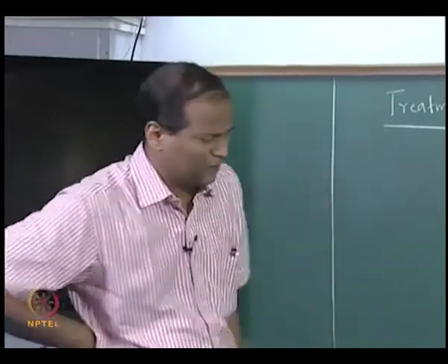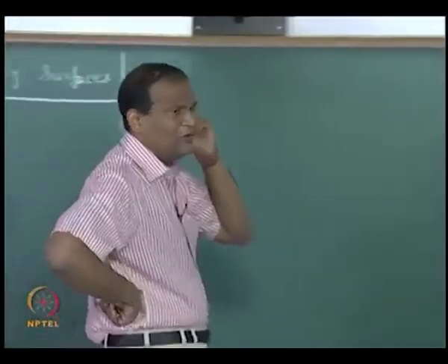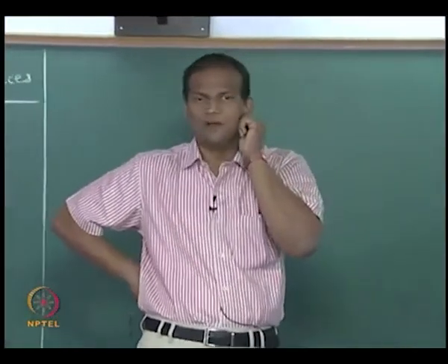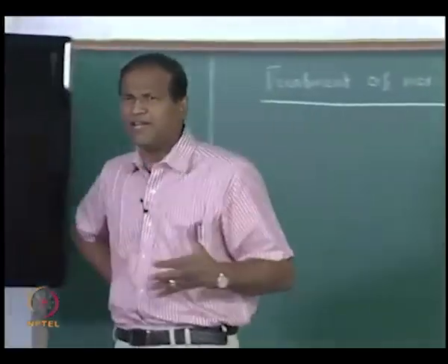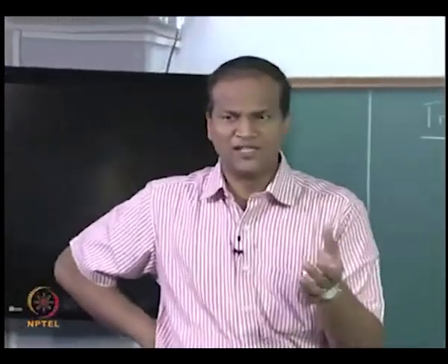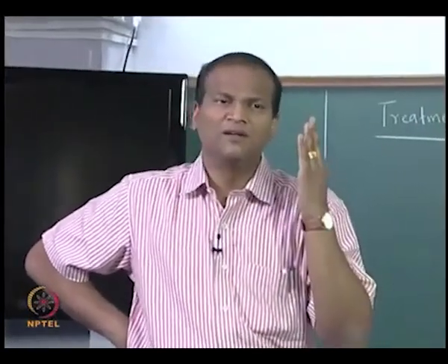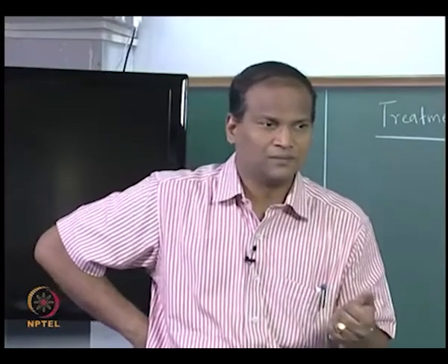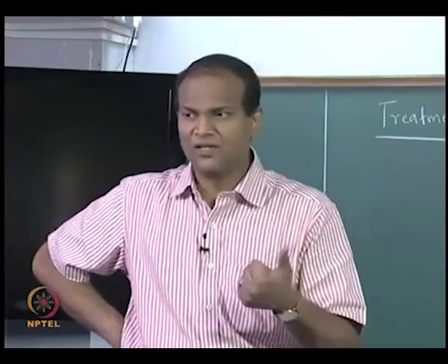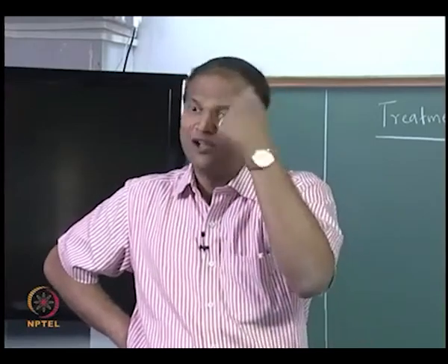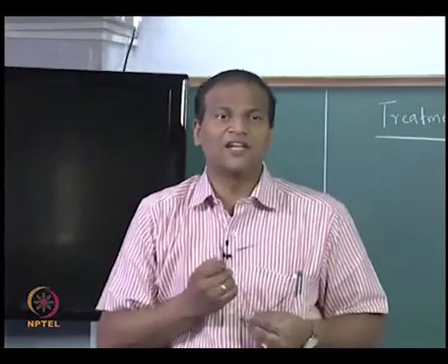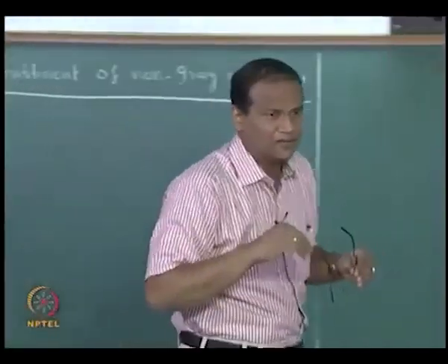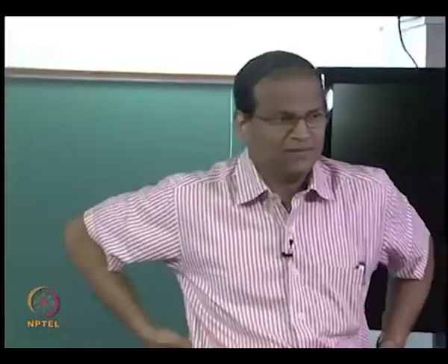We will go through the rigorous mathematical formulation, but the whole point is it is going to be computationally very expensive if the epsilon lambda versus lambda is very painful, correct, it is going to be computationally very expensive. That is, if your d lambda has to be necessarily very small, then you will have so many spectral radiosities for each surface. If you have an n surface enclosure, previously you had n radiosities, now for each surface you will have m radiosities corresponding to how many intervals you are dividing epsilon lambda. Are you getting the point? Therefore it will be computationally very challenging, okay.